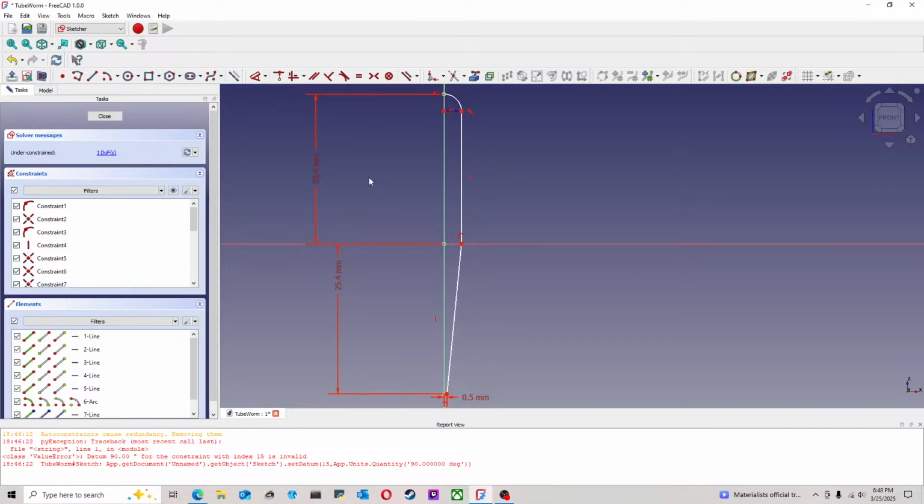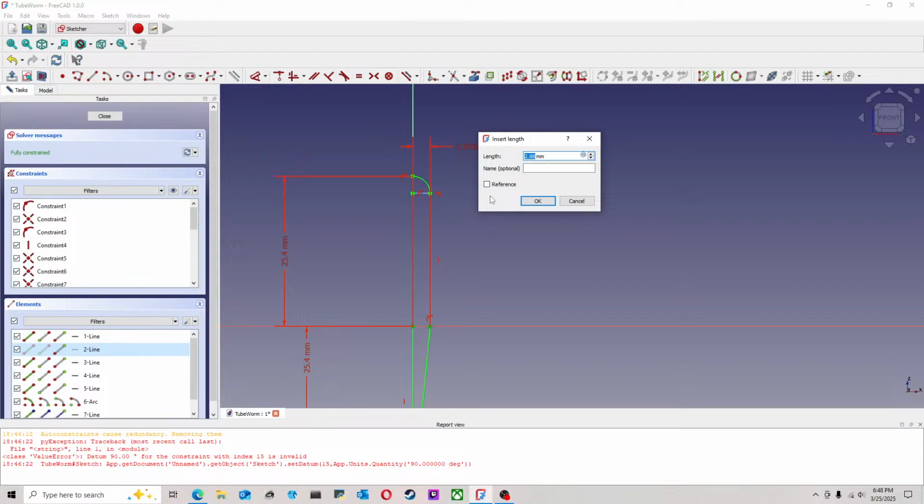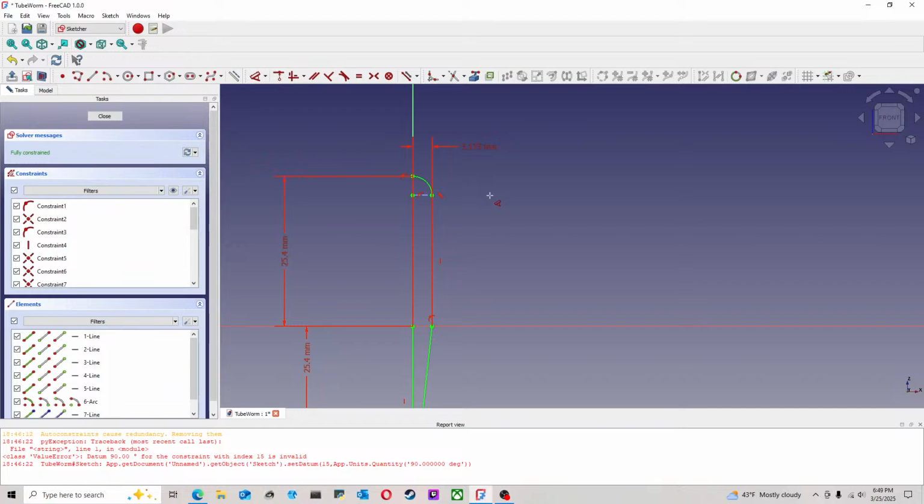So keep that in mind if you're going to do this as a revolved section. And doing these worm style baits as a revolved section is the way to go. So I'm going to go back here, and I want the bait to be 1/4 inch in diameter. So I really want this length to be 1/8 of an inch. And to tell FreeCAD that, I'm going to do 1/8, 0.125 times 25.4. And FreeCAD will do that math and calculate that.